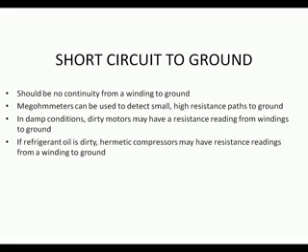Current flow through the winding increases. If the short is in the run winding, the motor may start, but the current draw will be very high. If the short is in the start winding, the motor may not start, but excessive current will be drawn. Now, sometimes these shorted motor windings actually touch ground as well. In that case, you'll have an electrical charge to ground, which should trip a breaker.